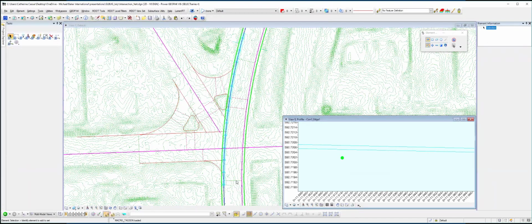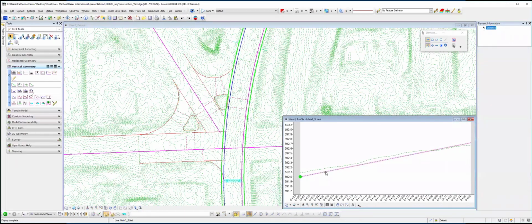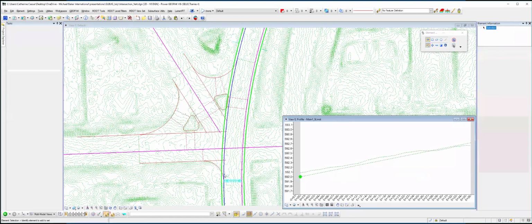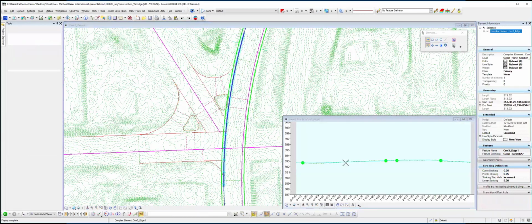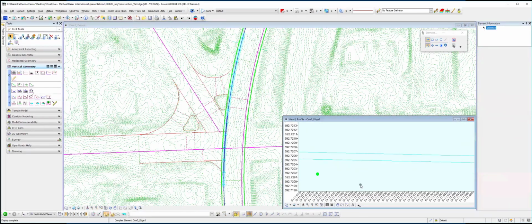And you notice this one here is a 2%, and I'll show it to you. I took from the alignment a solid 2%, which is what this roadway is supposed to be doing. And this is the active profile of that point. And this line that I created, I now have this issue. I have 3 different locations. Okay, I've got the south point, which is I know the 2% from here. That's that point right there.